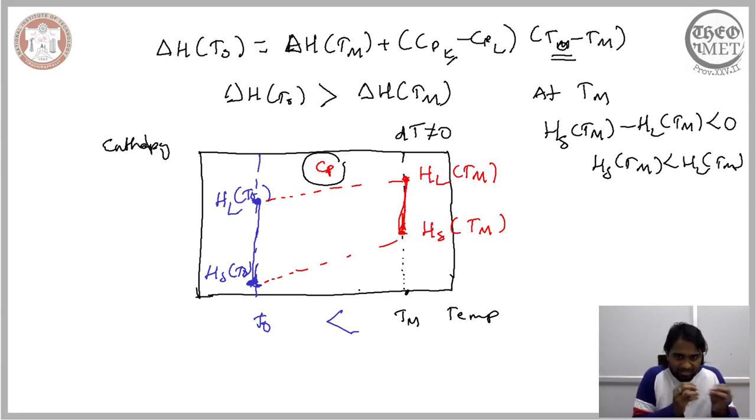We have considered the basic terminology associated with thermodynamics, and we have considered the first law of thermodynamics. Now the first law of thermodynamics has helped us understand how, with the change in the temperature, the driving force for a given phase change changes. We have considered two isothermal phase changes, and the phase change here is solidification. We saw that with change in the temperature the corresponding driving force changes, and this driving force is being expressed in terms of the enthalpies.